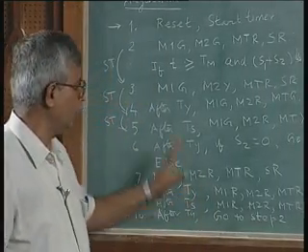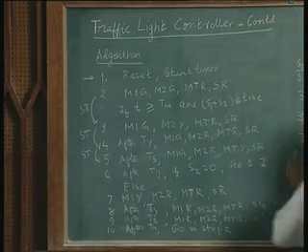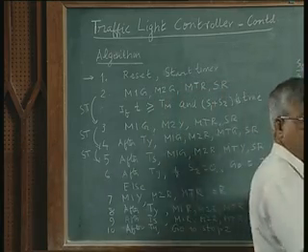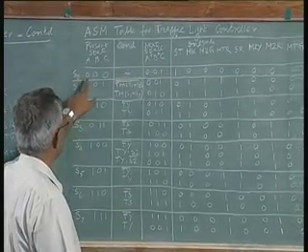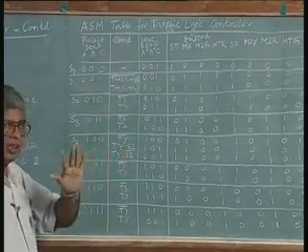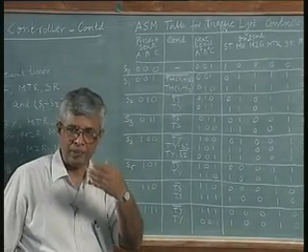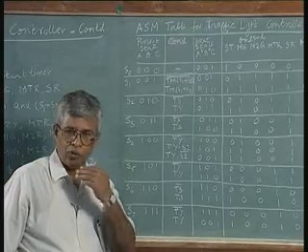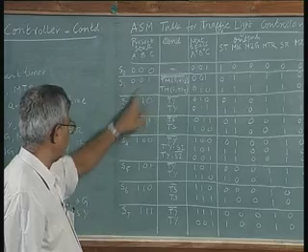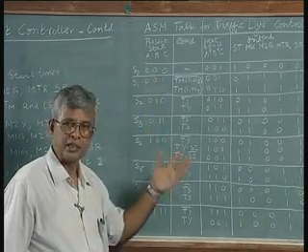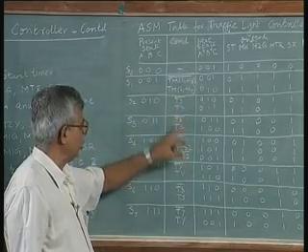Okay. Now, with this you go to this table. You are not expected to memorize this table, it is a huge table as you can see here. There are states here S0 to S7, each state we have taken a binary assignment, it is called natural binary assignment, and without any specific guideline for states. S0 corresponds 0 0 0, S1 0 0 1, S7 1 1 1, 8 states, 3 variables, we will call them A, B, C. The conditions are very simple.